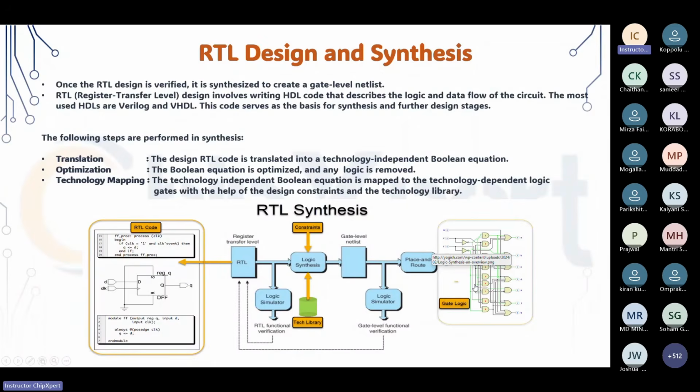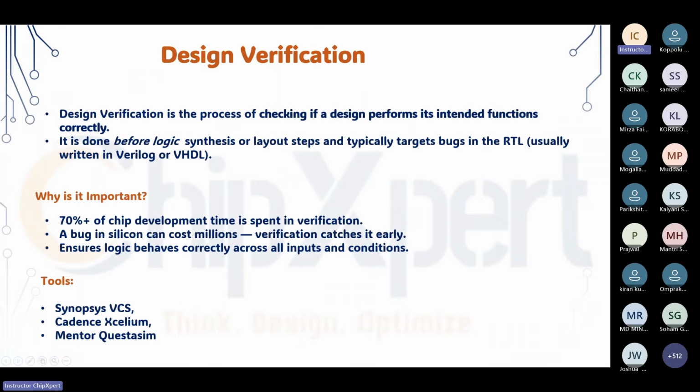Here there is a process where the design people design completely at the gate level. Again, it is functionally verified to check whether it works as per all the test cases they have given, meeting the requirements of the chip or not. Then they validate and catch the RTL bugs in the design.